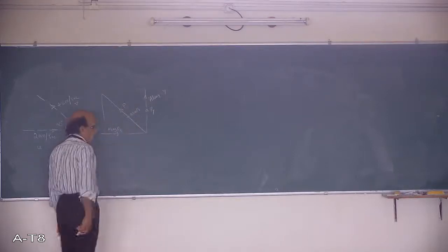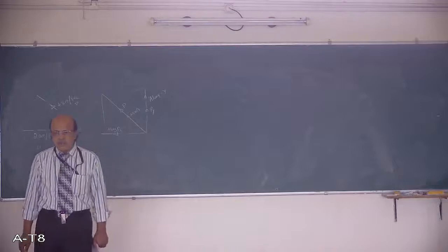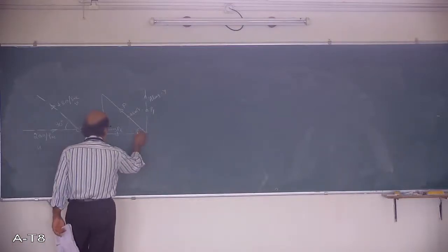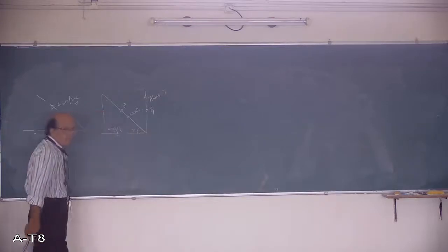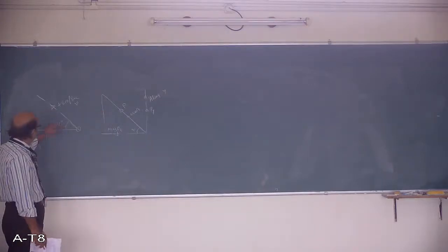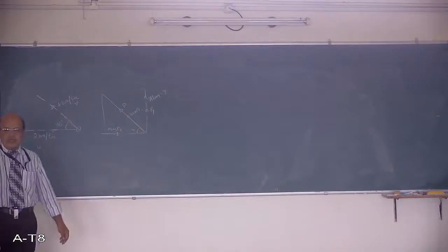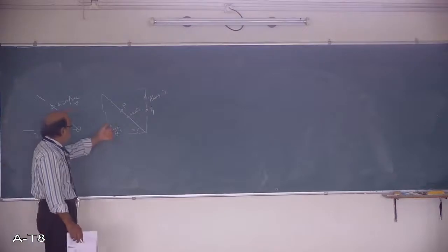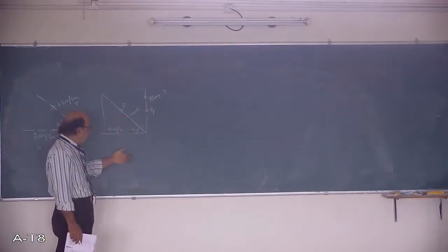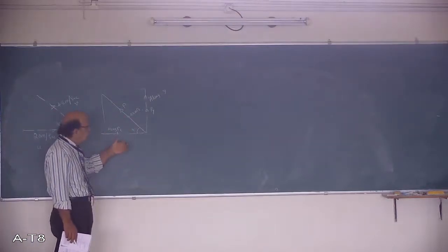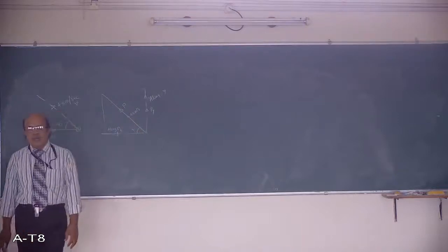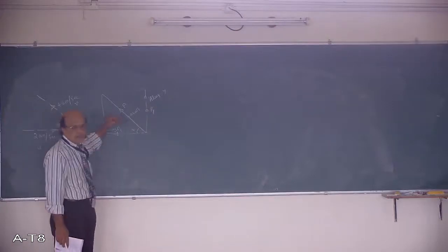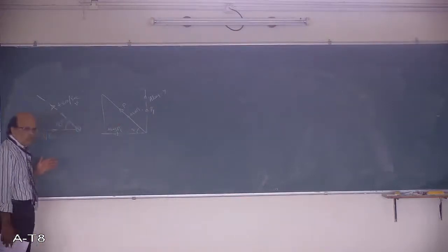We will get the net force exerted, that is P, in this direction. We will get the angle alpha at which he has to apply it. The bat is required to apply force at which angle, so that the ball can move with a velocity of 48 meters per second at an angle of 30 degrees. We have to apply the average force P. For that I have to calculate the component of force in the x direction, the component of force in the y direction, and then work out the resultant. That resultant is P, which is required to be worked out in this problem.